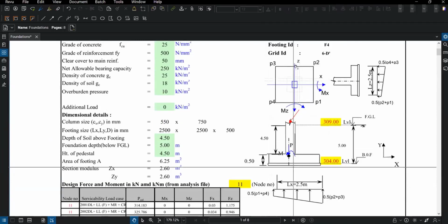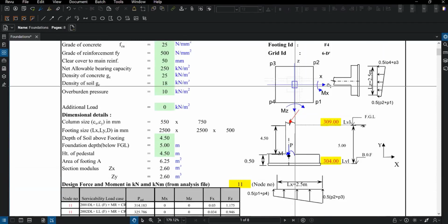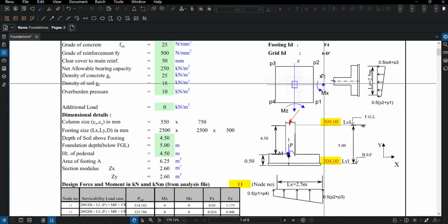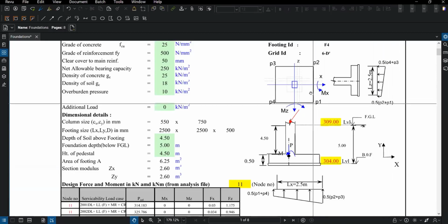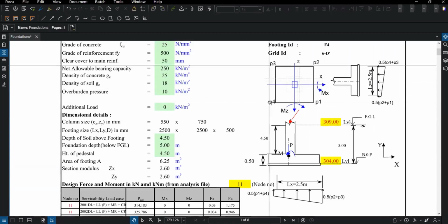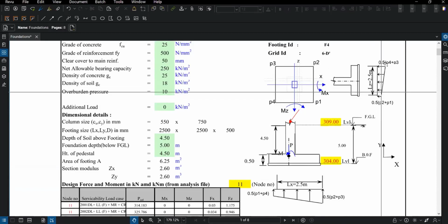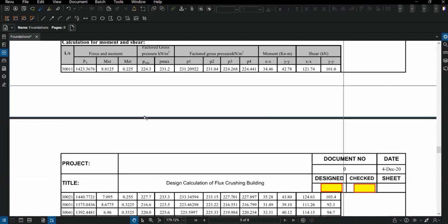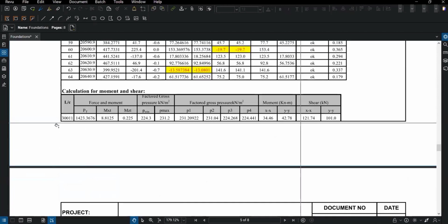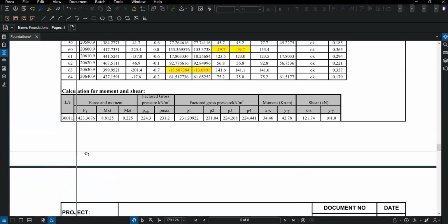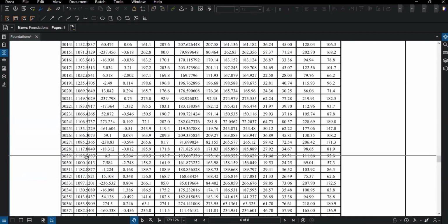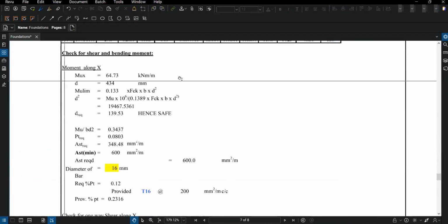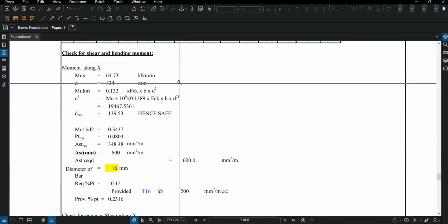P1 plus, okay, this section is vertically cut, this section is horizontally cut. So you can see that P1 plus P2 is average for this end, and P3 plus P4 is average for this end. And this becomes basically a slab with varying load, and bending moment and shear force calculations from that is pretty easy, right? We have arrived at the bending moment and shear force calcs with our strength load combinations, and have considered the maximum for designing the moment and the rebar.